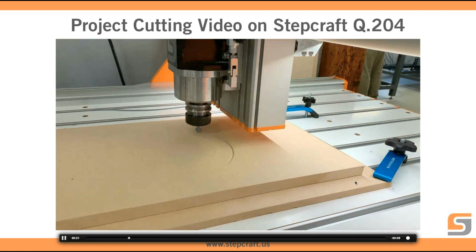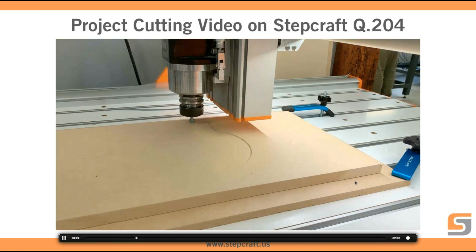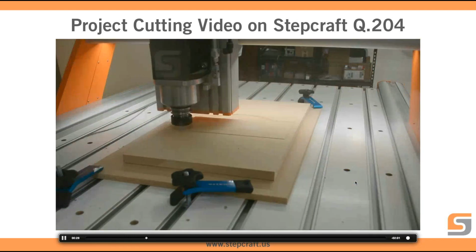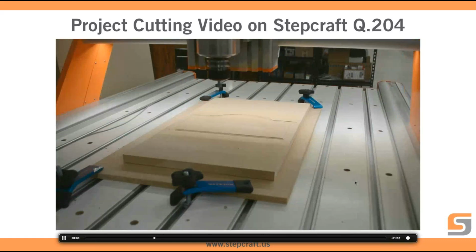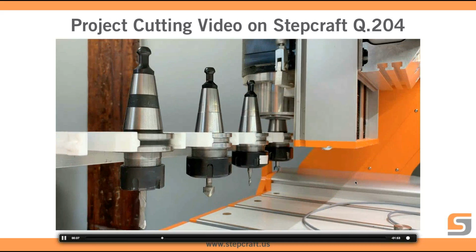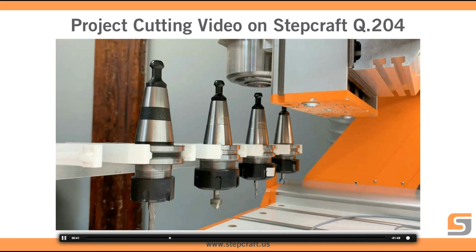So we're going to do 2 passes with this end mill, mainly because this end mill's old and it's kind of not as sharp as it used to be. So I could have done it in 1, but we just get a better result when we're using it with 2. I bought it off Amazon. It was a really inexpensive center point end mill, or center point roundover.